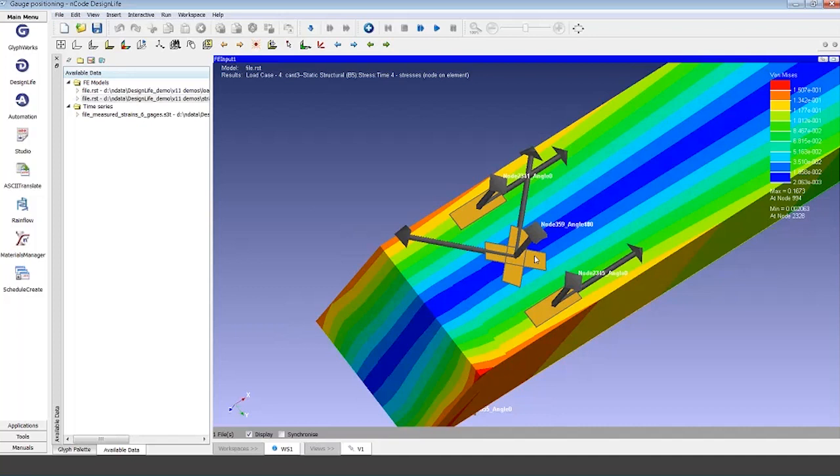Now, the whole process, if we want to figure out what loads are passing through our structure: step 1, figure out where to put gauges. Step 2, go record that strain data. Step 3, back calculate the loads from the measured strain data. So we're still focusing on step 1, which was where should the gauges go. Here we have a candidate set of, we could put 6 strain gauges in these spots. I think realistically, no one will stop at this point.